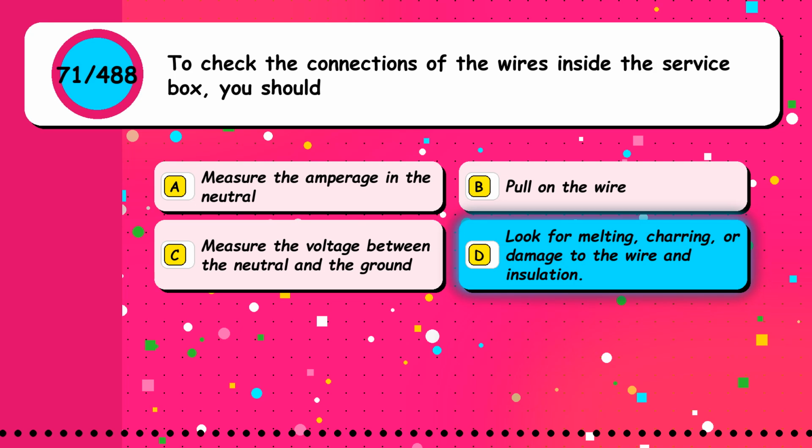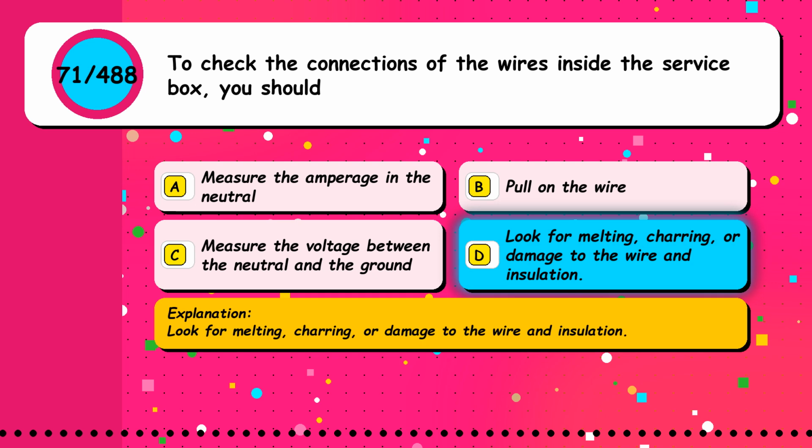The correct answer is option D, look for melting, charring, or damage to the wire and insulation.